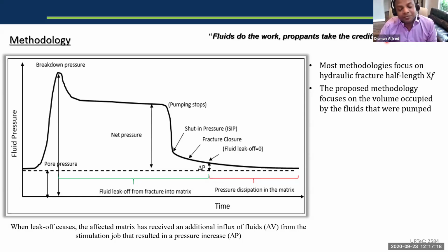That's all it's doing. Now the fluids are the guys who are going inside, doing the dirty work, and getting the hydrocarbon, displacing it, changing wettabilities, and coming back with it. And the proppants, all they do is sit there, getting pressed, and get the fluids into the wellbore, and suddenly the whole industry praises the proppants. When you look at things, everybody wants to plot EUR as a function of proppant per foot. It's good, but seldom do you see EUR as a function of fluids per foot. If you plot that, you will find an equally interesting correlation.